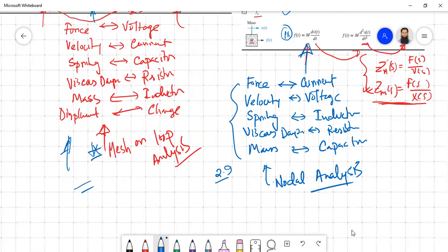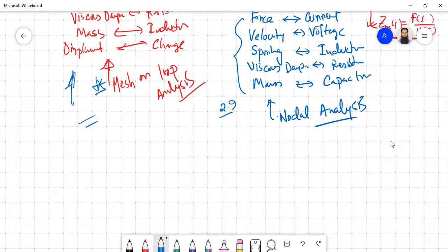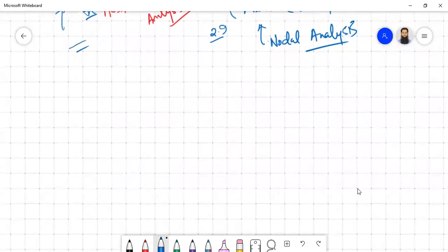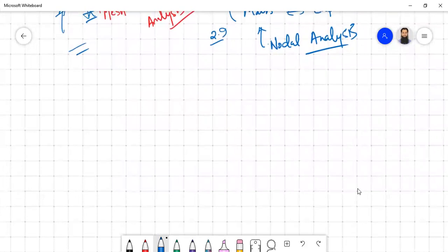So now the first thing is how to apply this. First of all, just like the electrical network, where we always start with the RLC network, in the mechanical domain as well we have a similar network, which can be called the mechanical RLC network. But the mechanical system requires a differential equation to represent it.